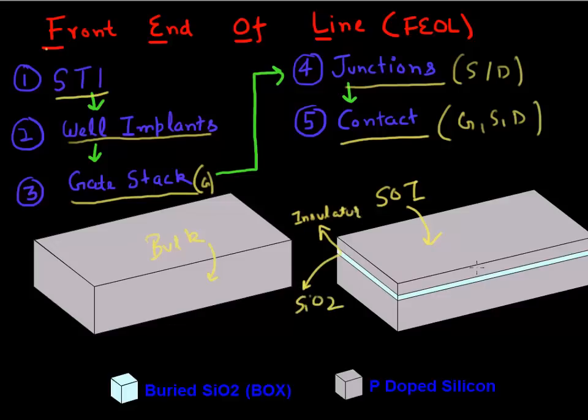And then this thin layer of silicon is placed on top of this insulator, hence the name SOI, which stands for silicon on insulator. So this silicon layer is now on top of the insulator, or another way to look at it, separated from the bulk of the wafer by this insulator.